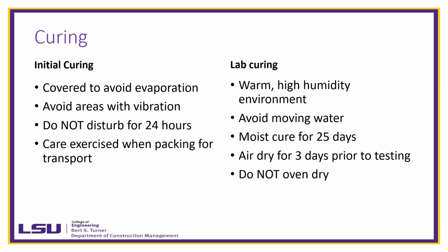You want them in a high humidity environment. Avoid moving water and any kind of fast moving air. And then you moist cure them for 25 days. You pull them out and then you air dry them for 3 days prior to testing. Do not oven dry them. And then once they're dry for 3 days, you can use unbonded or bonded caps, and then you break them like you would concrete.